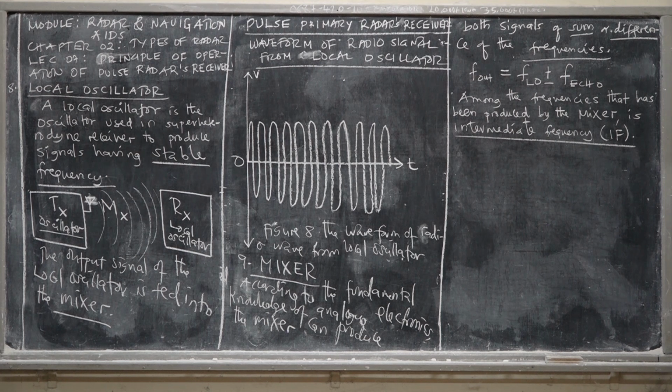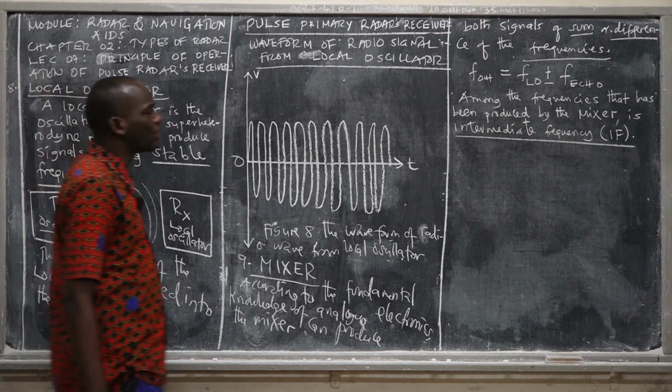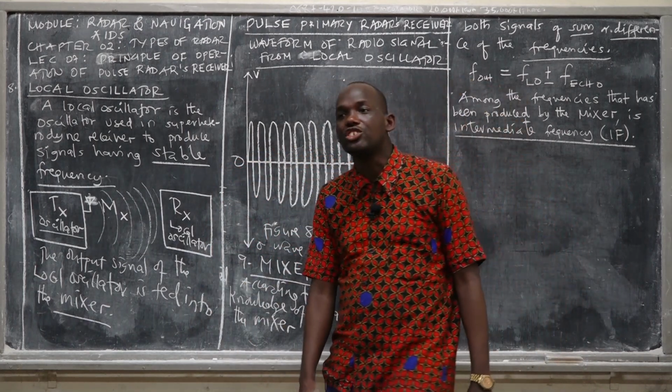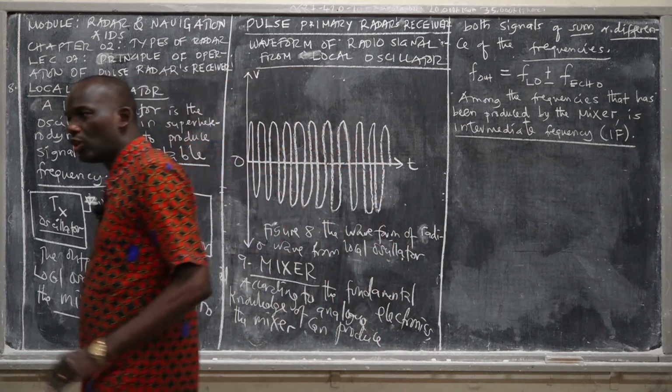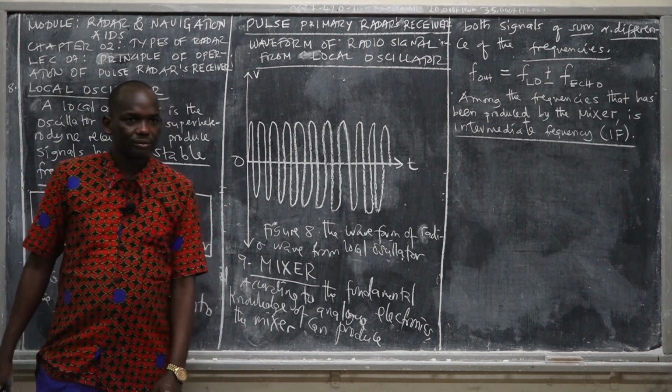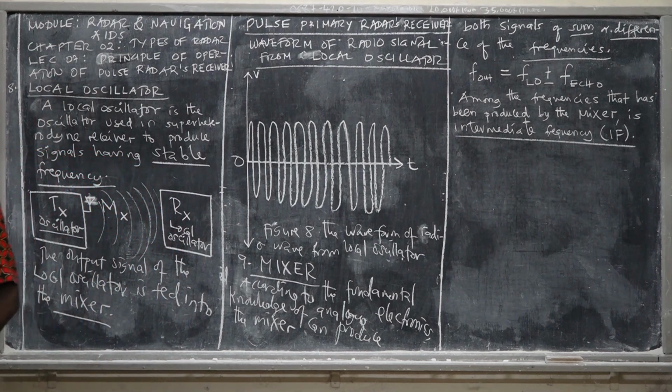Remember that when we were going through different videos of the different types of radar, one of the radars was operating with a frequency of 2 gigahertz up to 8 gigahertz. Right? So gigahertz is one of the spectrums, or one of the frequencies in radio frequency. So in the mixer, they receive the echo possibly at 2 gigahertz. Once it has been fed into the mixer, that frequency will be lowered from the RF into the intermediate frequency.